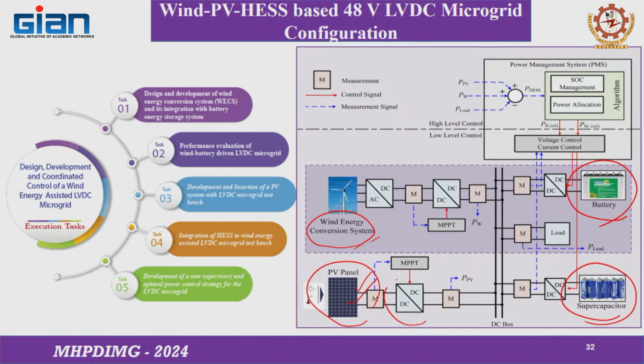Okay. So, here we will be going for this DC to DC converter, this will be the storage DC to DC converter. And for the supercapacitor again we are going for this DC to DC, this BDC. This topology is also called the bidirectional converter that I have discussed just now. Here we are going for this active topology, active configuration you can say. There are other configurations also, semi active, passive, but we are not discussing those things.